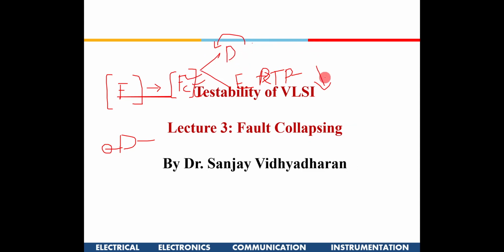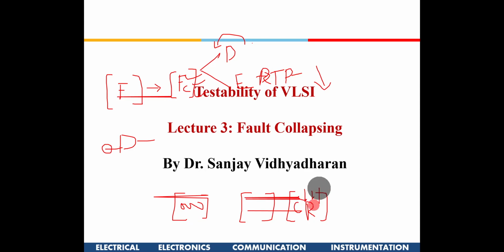So this is all about testing. Finally, what should be the output? There is a fault list, and then there has to be a test vector for each of these faults. And there has to be a matrix which gives me the correct results. What is the correct expected result? If I give 0, 0, 0, the correct one is say 1, 1, 1, and this matrix should be available to me. Only then can I detect these faults. And if it is not correct, then which gates are faulty? So this is the final thing which I want. Is it understood?